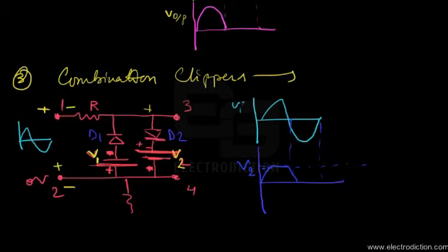As a result, the voltage V1 appears across terminals 3 and 4. As the output was slowly beginning to vary with the second half of the input cycle, it gets clipped off at V1 and then recedes again, as does the input signal's second half cycle.